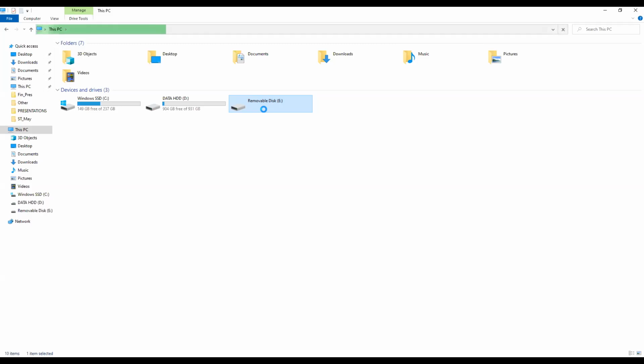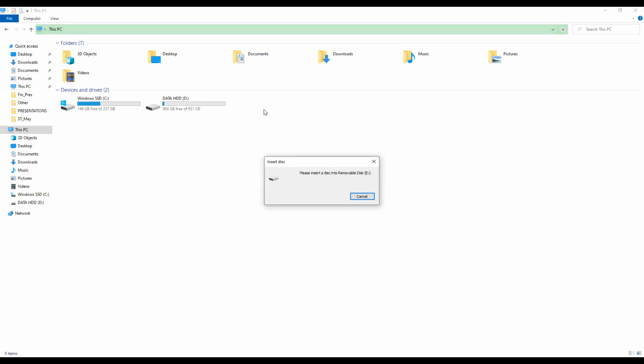And most likely we have some driver problems, because this micro SD card can be used normally, can be used correctly with the help of the original driver. Probably the initial firmware of this micro SD is not very good, and when the Windows driver tries to communicate with this micro SD card, it gets a failure, the drive couldn't be initialized correctly, and we get an error.